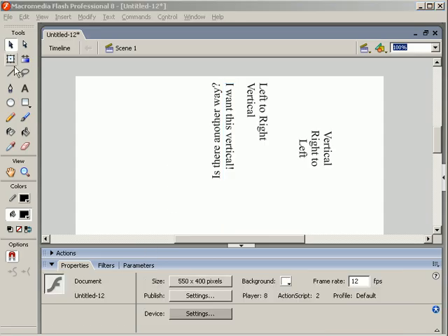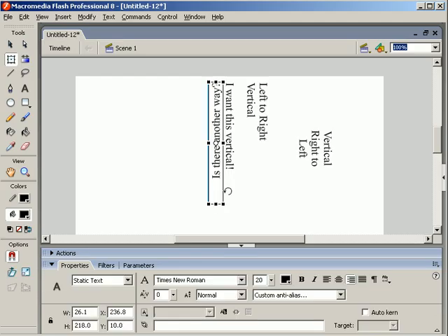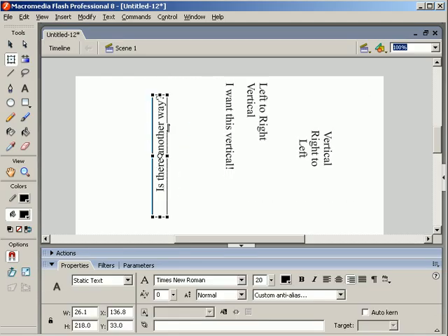If you're going to use that free transform method, just be good and sure that you only select the text that you want, and also be good and sure that you're not modifying it, like skewing it in any way, because then you're going to get all sorts of messed up, and it's not going to necessarily match the properties that you have down here. Another thing to watch out for is if you resize it, the letters will get bigger and it won't match your actual text properties.